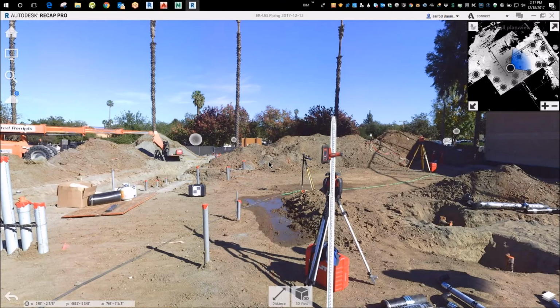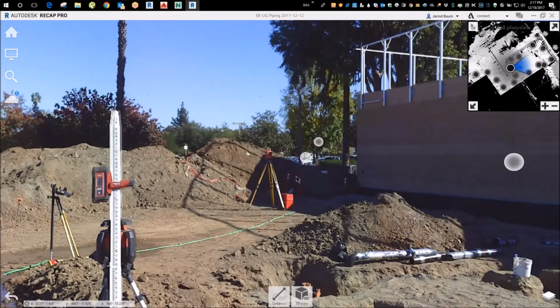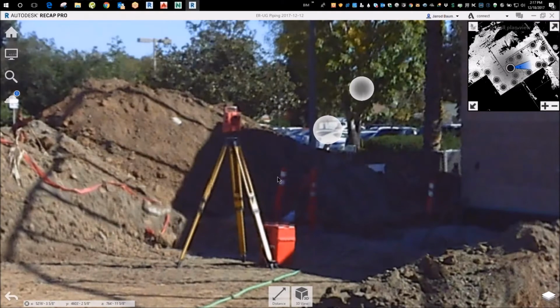And sometimes they give these guys grid lines, and that's what a plumber, their total station's simpler. It just wants 2 points. And you say, I'm giving you this one and I'm giving you this one, and you shoot them and you say that's grid line intersection this and this. And if the measurements are right, it's happy, right? If it matches the CAD file, they're good. There's no way of knowing, is that really on the right coordinate system? That's a full survey total station, which is what ours is.